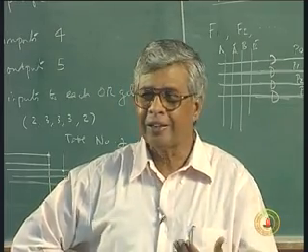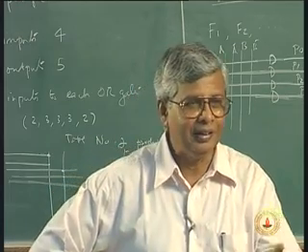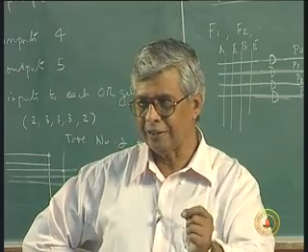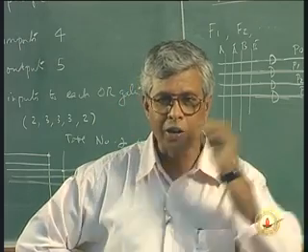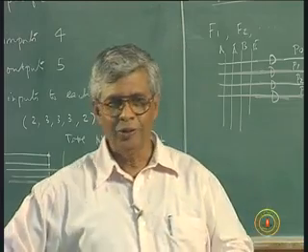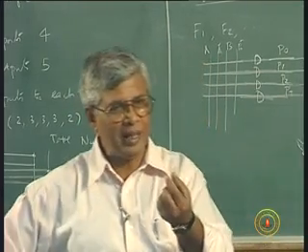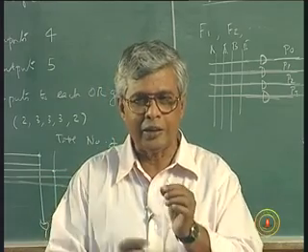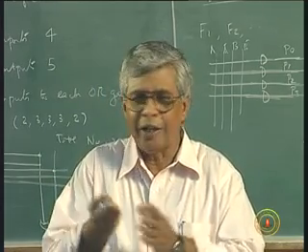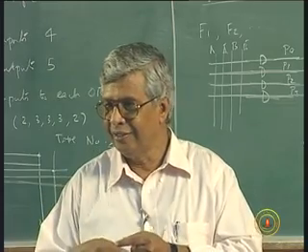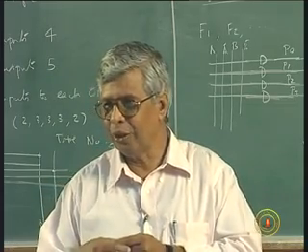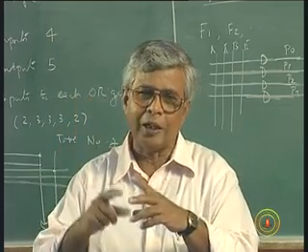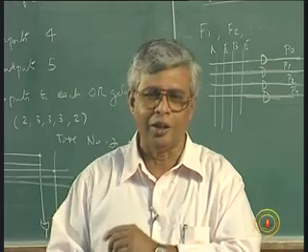It should have a mechanical ruggedness, it cannot be brittle, it has to be put on a base which will stay, and then I have to make connections, because when I have a million gates, naturally there will be a large number of inputs and a large number of outputs. So I will have to provide for all those inputs and outputs. That means I need a base with different pins for inputs and outputs, and they cannot be micron dimensions. How do you physically connect it to another device or a computer? So I need to have a minimum size. So when the size becomes larger, all our original concepts of size saving have to be rethought.